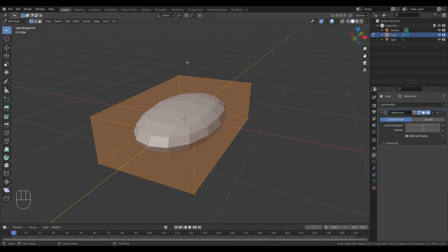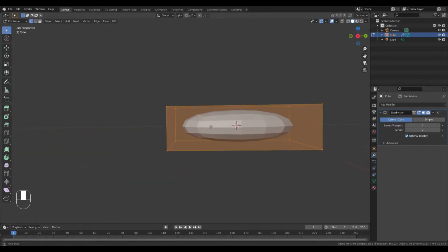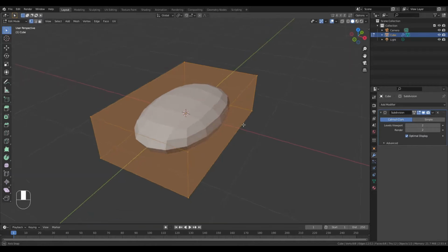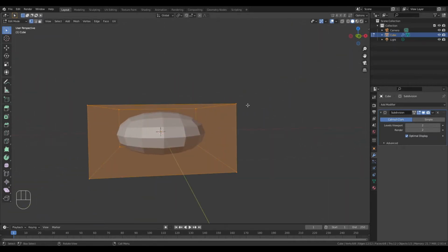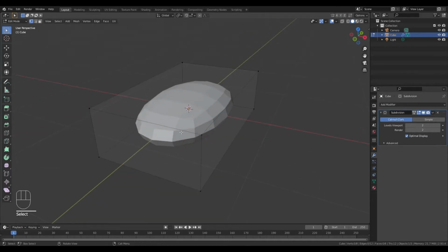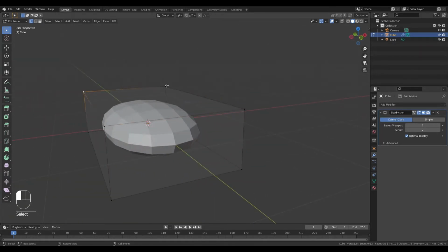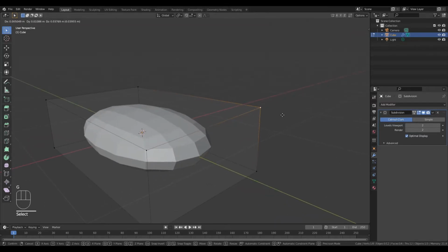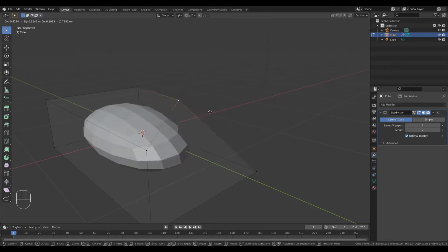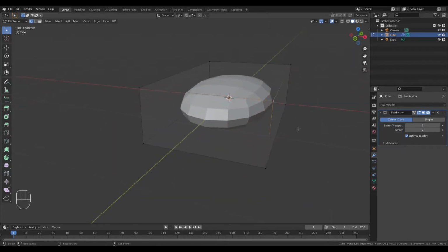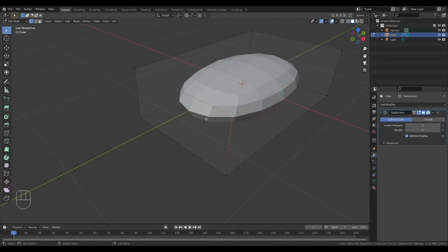So in orange here, because it's selected, you can see our original bar. But we can also see the mesh that the subdivision surface is giving us. So from this reference, this wireframe reference, the subdivision surface is calculating this internal object. And you can see that if from these points of the rectangle, if I start moving them, the internal object reacts to that. Now, what I want to do is tell the subdivision surface to not round the edges quite so harshly. And Blender calls that Crease Data.